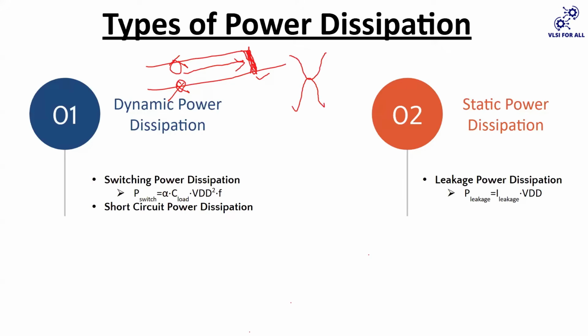Okay, but if you look at this, there is one factor which can drastically reduce the switching power. What would that be? Just from the formula, it's visible. Power supply. Why did you land on this? Because it's squared, so it does not have a direct linear relationship. It's the square of something.